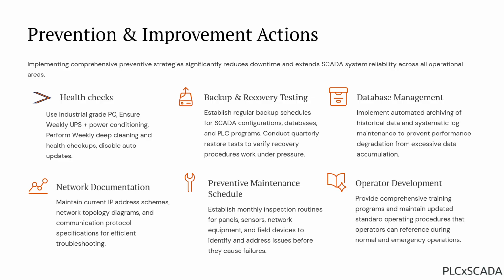Related to software: take regular database and system backups. Conduct a disaster recovery test every quarter. While designing SCADA, implement automated archiving of the database. Use a modularized programming style so that it will reduce the garbage code in the PLC or SCADA. Handle memory allocation of the log file in the SCADA PC.